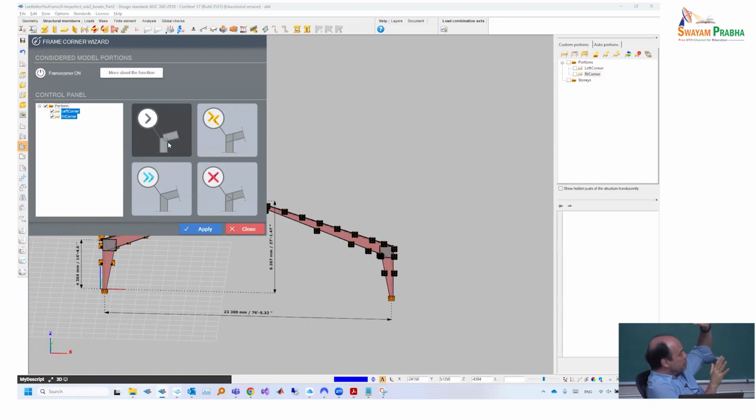So we still don't give any information about how the connection topology is made. The beam element transmits the warping deformation as it would by analogy. And as we saw, in the case of a box, this is completely wrong. In the case of the diagonal, this is more or less fine. And in the case of the combined box and diagonal, it's again completely wrong.